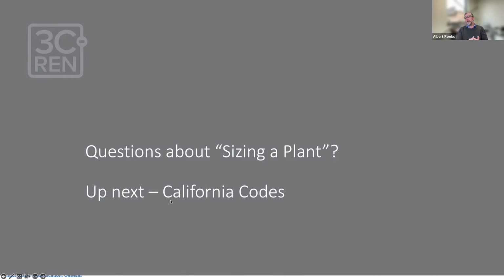When you look at a sizing and you say, okay, I need 85.5 kBtu capacity, then you actually have to go look at the heat pump that you're using and say, okay, if I'm using it in this climate, what do I need to do? Do I need to derate the heat pump in order to achieve that 85.5? So it's just looking at domestic hot water in the building, recovery and consumption, and then assuming that you're going to select equipment that will deliver that capacity requirement. Hopefully that makes sense to you.